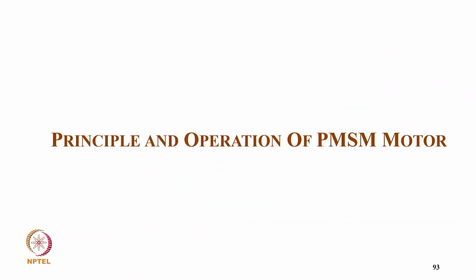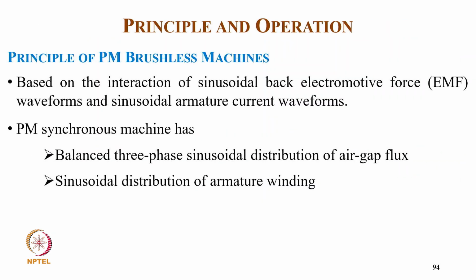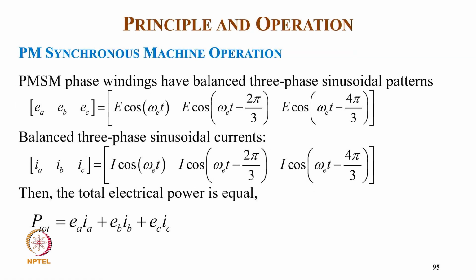Now coming to the principle and operation of the permanent magnet synchronous motor. Based on the interaction of sinusoidal back EMF waveform and sinusoidal armature current waveform, the permanent magnet synchronous machine has balanced three-phase sinusoidal distribution of air gap flux and sinusoidal distribution of armature winding.